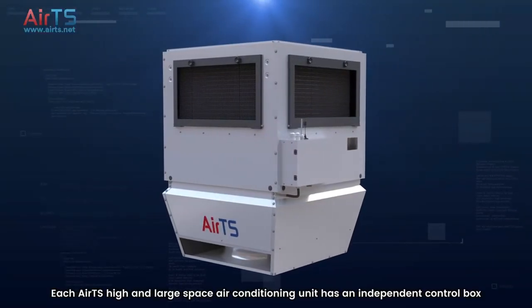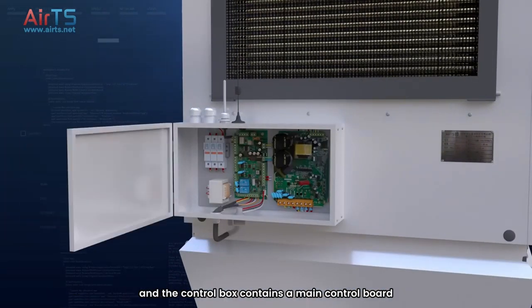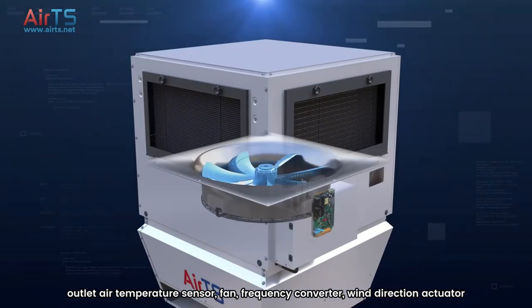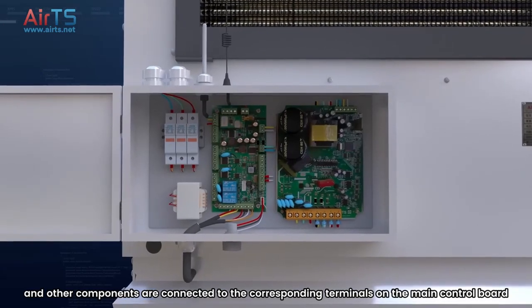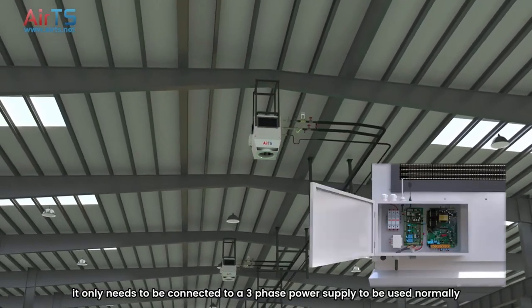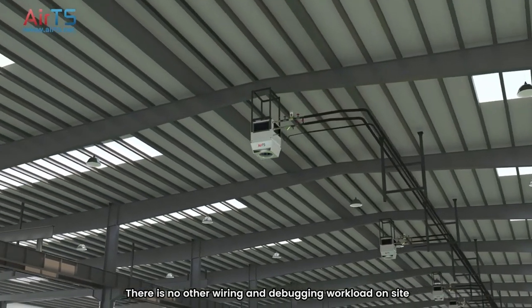Each AirTS high and large space air conditioning unit has an independent control box, and the control box contains a main control board. The control and communication cables of the return air temperature sensor, outlet air temperature sensor, fan, frequency converter, wind direction actuator, and other components are connected to the corresponding terminals on the main control board. All functions of the device have been tested before leaving the factory. When the device arrives at the site, it only needs to be connected to a 3-phase power supply to be used normally. There is no other wiring and debugging workload on site.